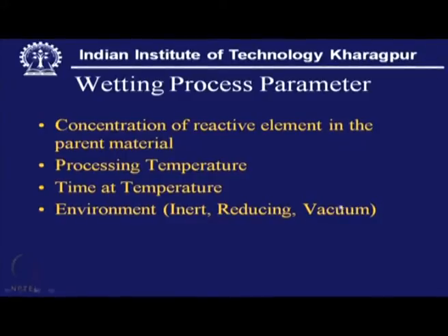In that case a vacuum environment is most desirable to promote wetting for this kind of material. Vacuum environment is always desirable, and it is not a rough vacuum, it is a high vacuum. In that case the titanium is prevented from getting oxidized, and it can be 100% utilized in promoting wettability by this reaction over the ceramic surface.